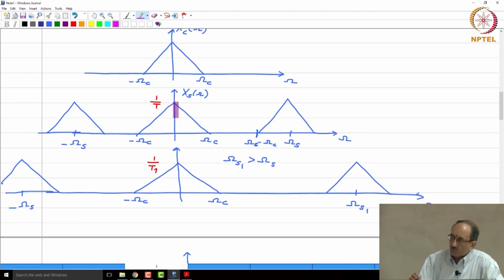So, all you need to do to relate this to the underlying sequence's DTFT is scale the frequency axis by Fs, right, that is all. And why does that make sense? That makes sense because this is 2 pi Fs. If you now scale this by Fs, this point will now get mapped to 2 pi, and the DTFT is nothing but 2 pi periodic, that is all, as simple as that.